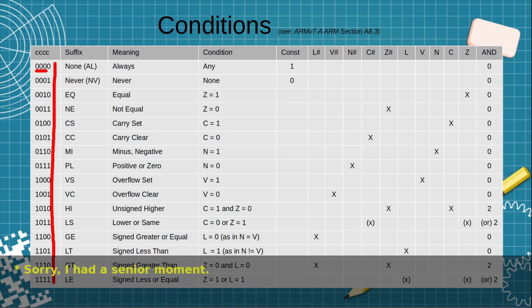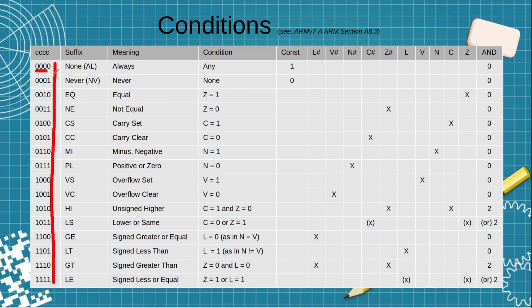All right, is that going to work? Yes, it will work, because the 1 or the 0 is going to come from this least significant bit. So yes, the least significant bit is going to determine whether or not it's buffered or inverted. And then the result of all of this evaluation is going to be the other side, which is going to be the output off the 74HC151. So yeah, that's going to work just fine.